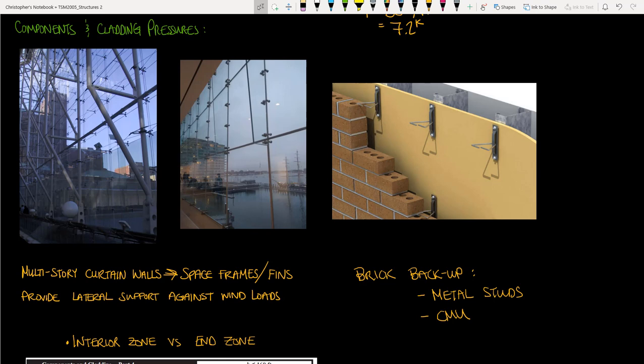In the previous video, we discussed wind loads from a strength design perspective. In this video, we will discuss wind loads from a serviceability perspective. To start, let's consider two common materials found on the facade of a building: a glass curtain wall and a brick veneer. Both of these materials are relatively brittle. We will discuss that term in more detail later, but for now, you can imagine how neither of these materials will be able to bend much before cracking. And so, we need to design a structural system to provide the total wall assembly with enough stiffness so that the architectural materials will not crack.